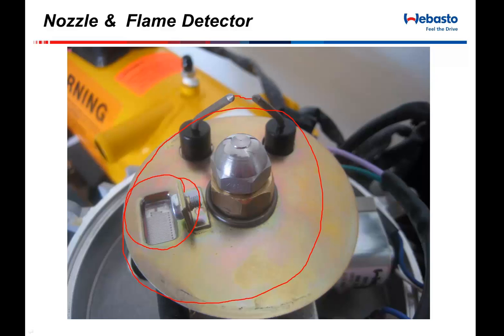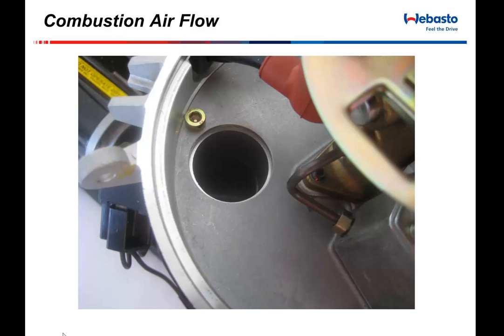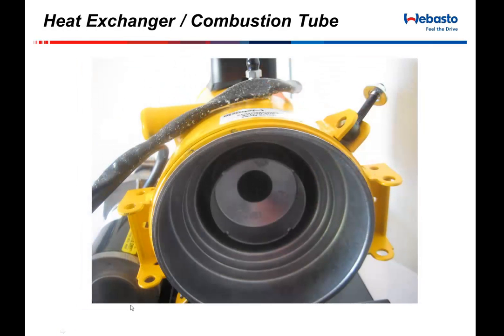And the reason for that is the air that we're using to burn is being brought in through the bottom of the unit. We'll look at that here in a second. But that air is coming out a hole which is at about 11 o'clock on that whole burner assembly. And then it is being shot into the heat exchanger on the outside portion here of this cup.